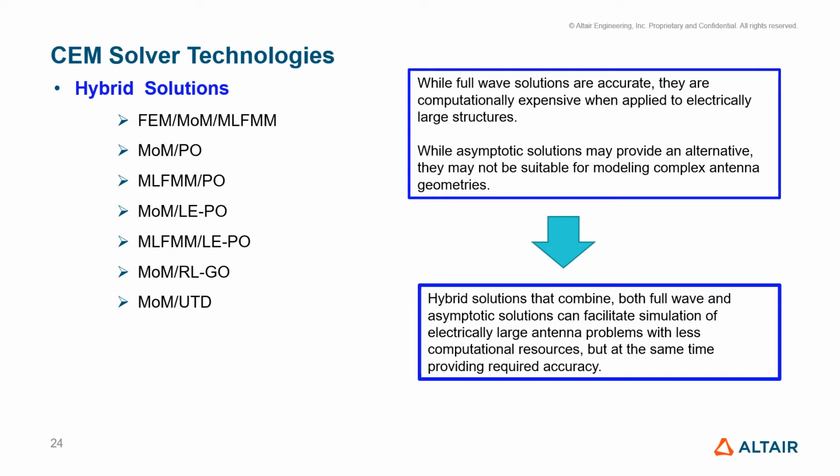In terms of hybrid solutions, we're going to talk about these methodologies in this current presentation. That is FEM hybridized with method of moments and MLFMM, as well as method of moments with the physical optics, MLFMM with the physical optics, same thing with LEPO, and as well as RLGO and UTD solutions.